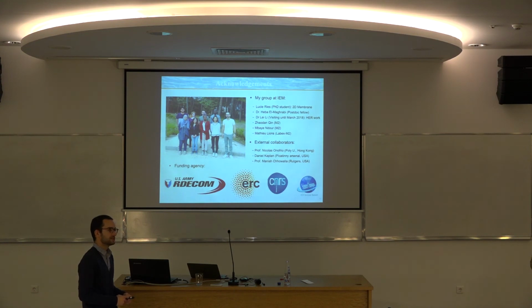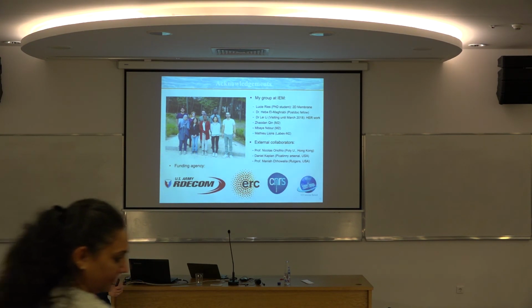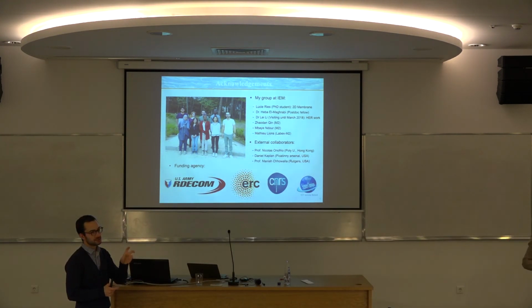No, we didn't have any evidence of this. I was very fast on this, probably too fast, but we synthesize by hydrothermal reactions, and the material is actually more amorphous from the X-ray diffraction that we observe. So what we did, to make sure it's highly crystalline and 2H, is anneal the sample at 800 degrees under pure argon. In this case, we don't make defects, but we recrystallize the material.